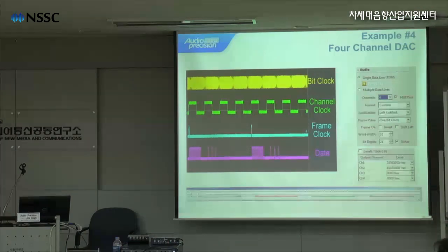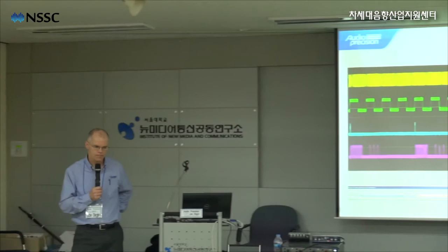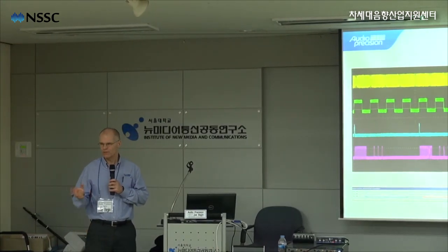With Bluetooth, it's a wireless connection and it uses a codec. The standard codec that's available really depends on the profile that you're in, right? There's a hands-free profile, which is low quality, 8 kilohertz or 16 kilohertz sample rate. And then there's the A2DP, stereo music profile. But the stereo music profile typically uses the SBC codec, or there are other optional codecs like aptX is one.